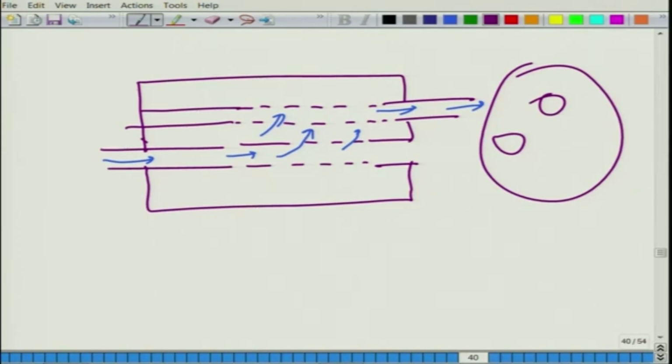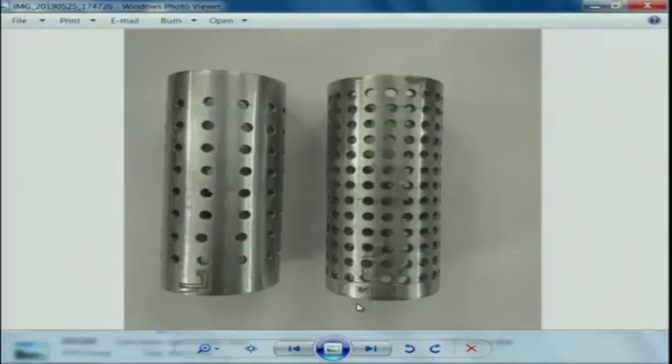Now, let me show you some nice photographs of the interiors of how a typical perforated element looks. So, we see these perforated tubes. These are something that we fabricated some time back. This is nothing but 2.5 or 3 mm MS steel pipes, and a number of holes, about 2 mm, 3 mm holes, were drilled at regular intervals, as you can see here.